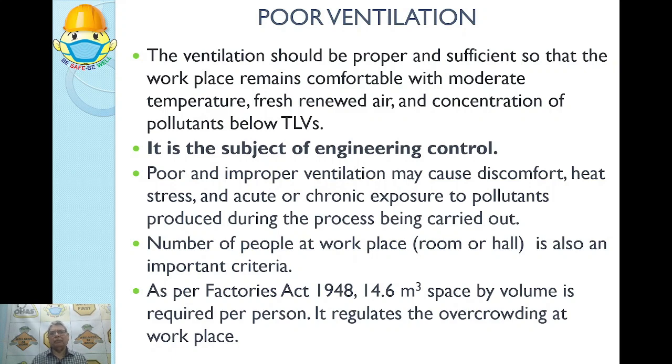So the ventilation should be proper and sufficient so that the workplace remains comfortable with moderate temperature, say from 20 degree to 28 degree. So it remains moderate, a fresh renewed air and concentration of pollutants below threshold limit values. So the ventilation should keep the place comfortable. There should be fresh renewed air, and very importantly, the pollutants should not linger on, they should be immediately taken out of the workplace. It is a subject of engineering control.